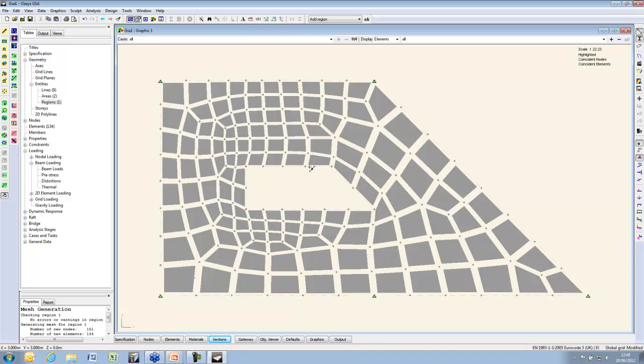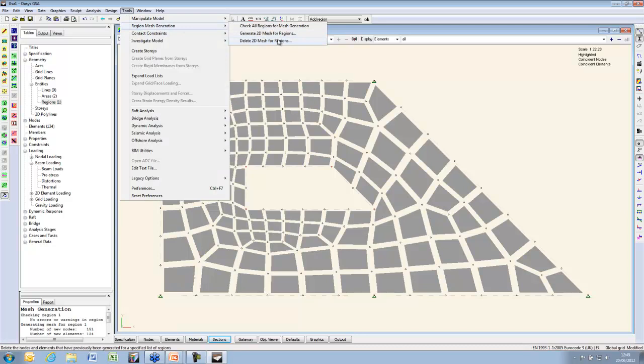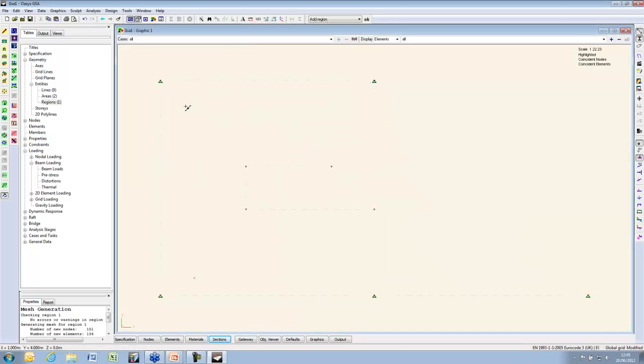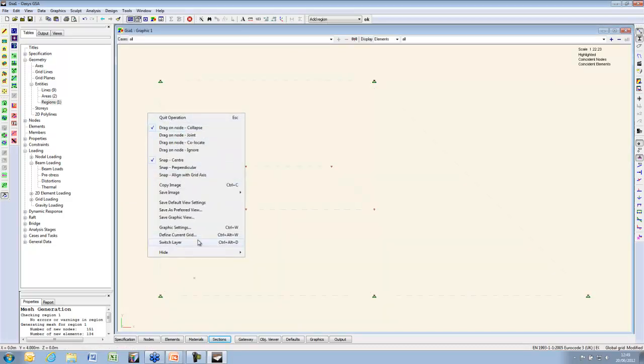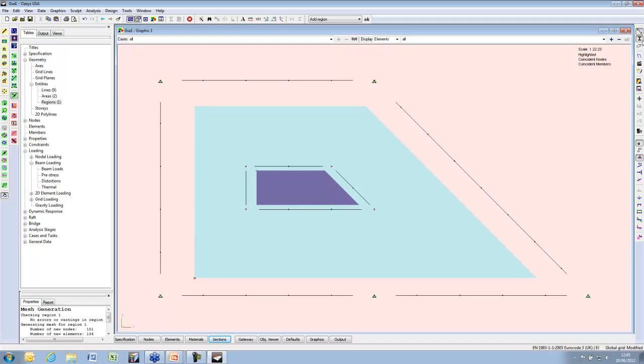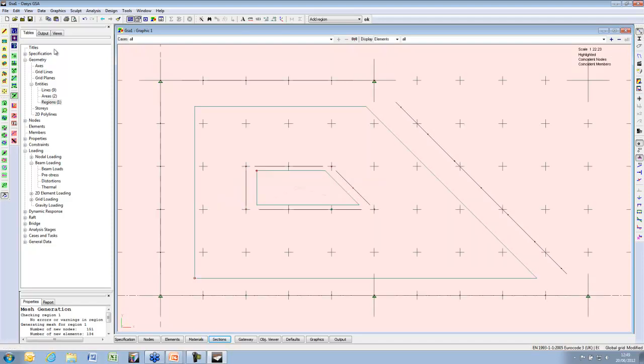Okay, now with this also meshing, obviously that's created a general mesh, but let me go back to the design layer here. Let's say we had a point in here which was going to be, say, a column coming down or so on. So I'm just going to add in a point.